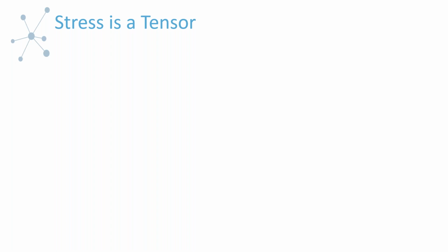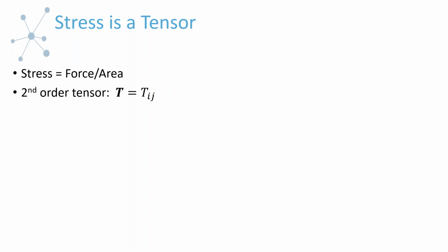Vectors, as you know, have a scalar component which defines the magnitude, but there also has to be a specification of the directionality. For velocity, you have a speed, but you also have to say what direction you are moving in. And for force, there's a magnitude and also a directionality associated with it. So it's the same idea, it's just that we need to be a little more specific and we bump it up to the rank of second order. Stress is defined as a force per unit area. That means we're going to have to say something about the directionality of the force and something about the surface area that this force is acting on. That's why it's going to be this second order tensor.